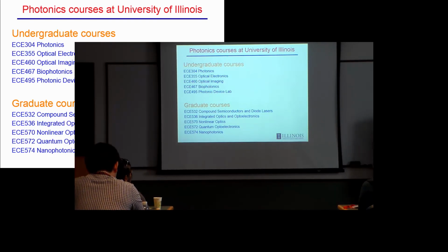So what are we doing today? You're texting, you're taking a picture, you're sending it through the internet. You're creating digital information, zeros and ones. Well, zeros and ones we use as a laser, the brighter and dimmer, that's our 0 and 1. We have a sequence in time of light pulses going down the fiber. But in multimode fiber, they're going down in all kinds of different modes, and they travel at different speeds. So you take a pulse in time, put it down the fiber, it gets to the other end, and it might not have the same bit stream that you started with.